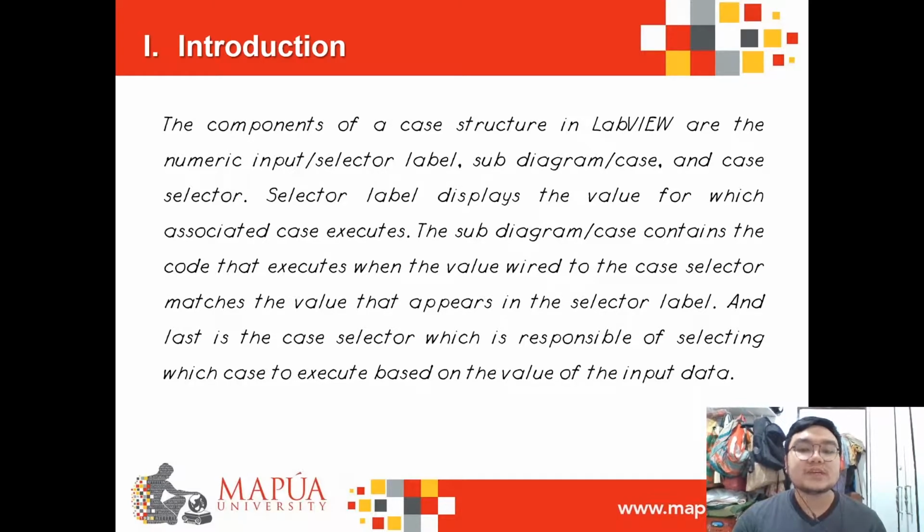The components of a case structure in LabVIEW are the numeric input or selector label, subdiagram or case, and case selector. The selector label displays the value for which the associated case executes. The subdiagram case contains the code that executes when the value wired to the case selector matches the value that appears in the selector label, and last is the case selector, which is responsible for selecting which case to execute based on the value of the input data.